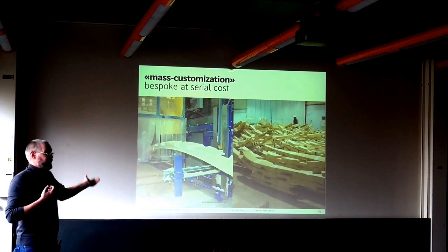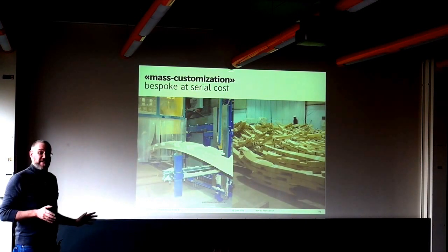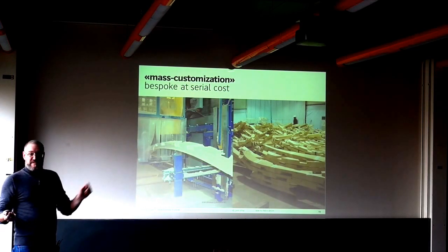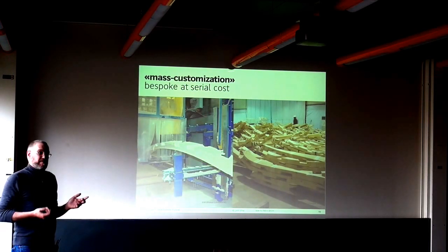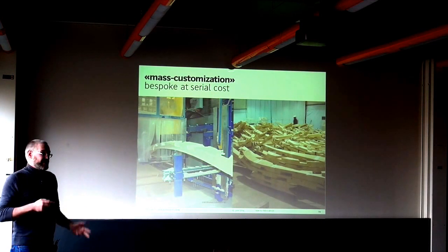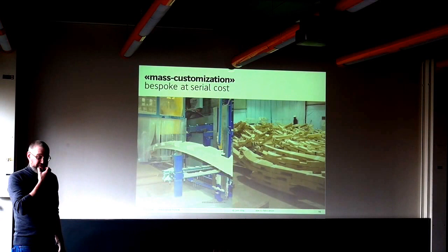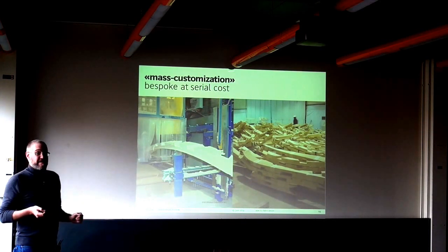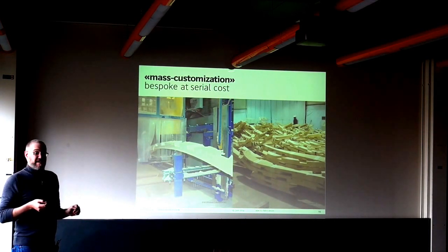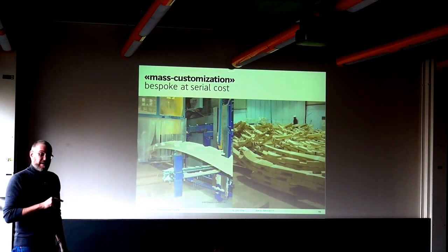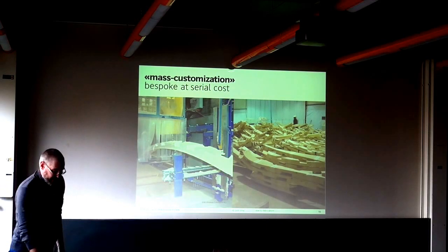Someone has to translate the geometry that comes out of whatever design software you have into control commands that the CNC machine is reading, which means usually NC code that only holds X, Y, Z, A, B coordinates for the 5 axes of the machine, or however many axes you have. And the translation between one and the other is something that is tricky as soon as you go away from standard components. I'll come back to that in a minute.